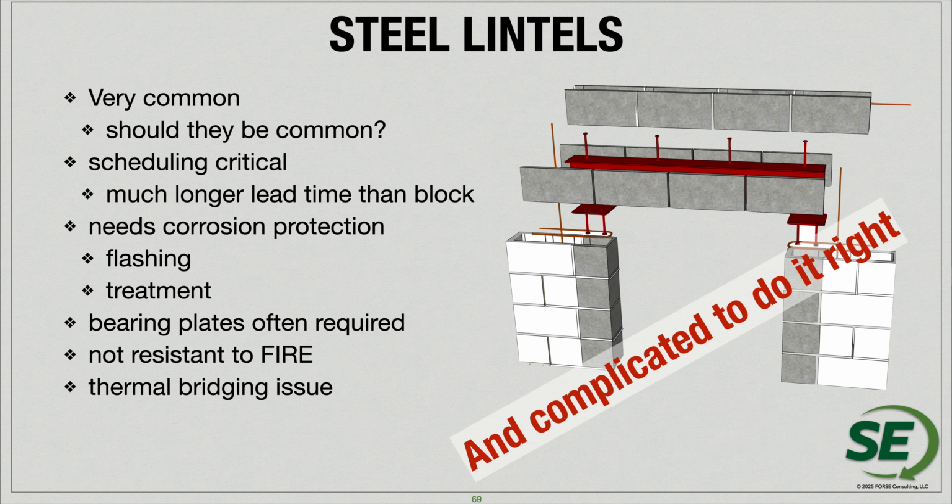It does cause massive amounts of loads if it's not allowed to slip or slide at those bearing locations. So the thermal bridging does become more than just a transfer thermal bridging, but the thermal loads become an even larger issue, which is why we see a lot of potential problems using steel lintels.